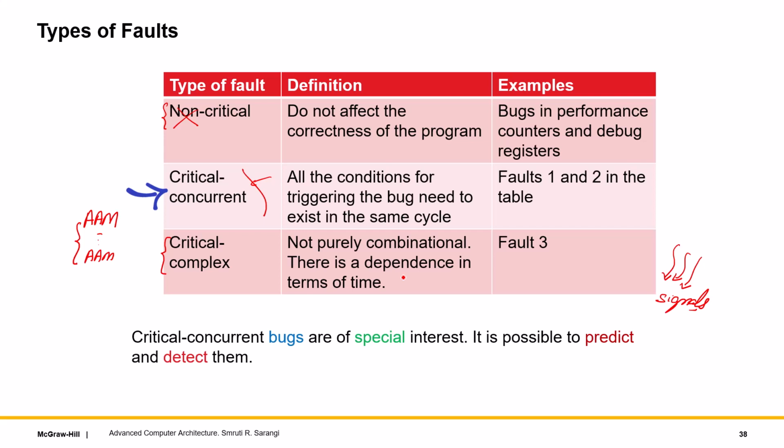And also, historically, a bunch of processor specific things like a certain power mode or certain reinitialization mode, if that also has been involved, all of that could be tapped. And after tapping, we need a programmable combinational unit which can say that, look, yes, if signals 1, 3, 5, 8, and 10 are true at the same time, it could lead to a buggy situation. So pretty much that is how you would predict. But this is kind of predicated upon the fact that all of these events of interest are being collected in hardware in the first place.